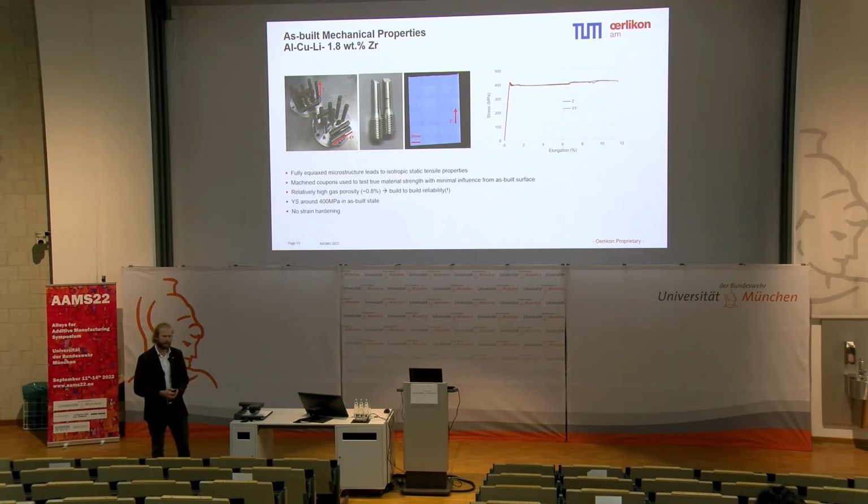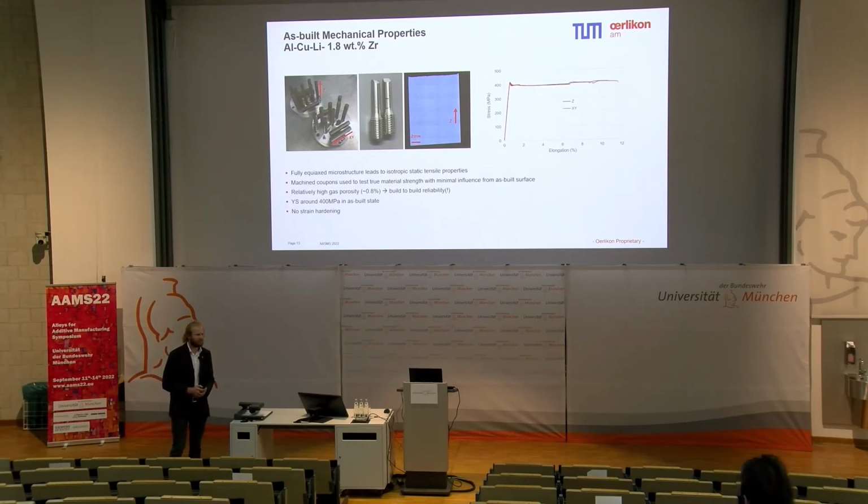Maybe that has to do with the gas flow more so than the laser optics. But I think it's important to repeat some of our DOEs and ensure that we can really reliably print with those density values, because I know we all want to publish papers here, and when we get a great density value, that's great and we can move on. But in terms of transferring this to other machines, or to production, we need to do more testing.